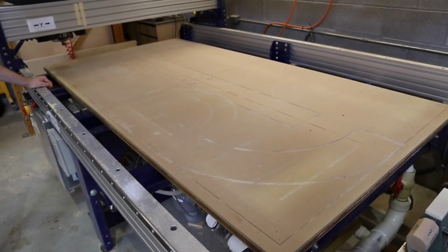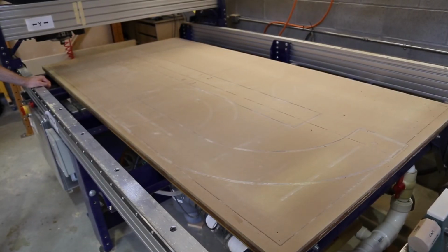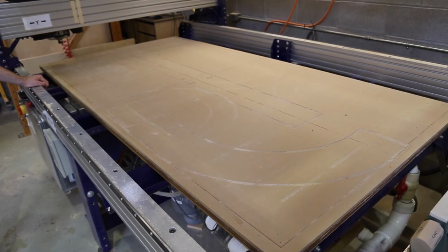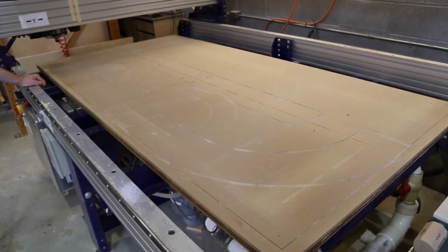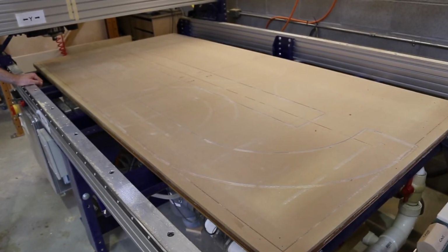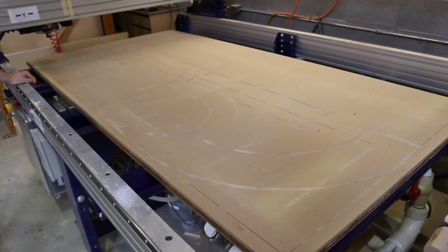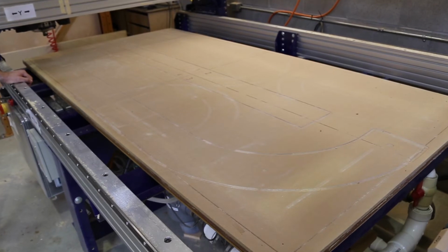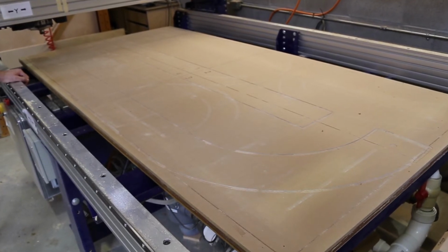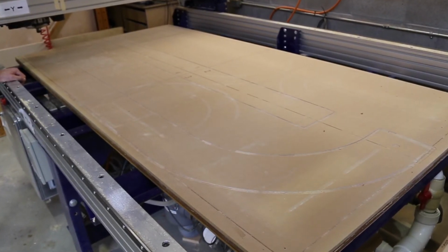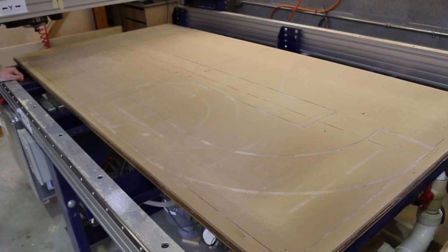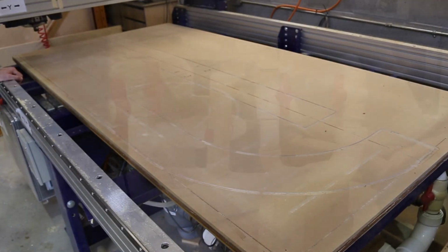To secure material while cutting on the CNC, you may not use steel clamps or screw anything directly to the spoil board at any time. Flat material of sufficient area can be held by the vacuum to the MDF spoil board. The vacuum can only hold flat material. It has limited ability to hold warped sheets, bowed solid wood, and parts with small surface area.